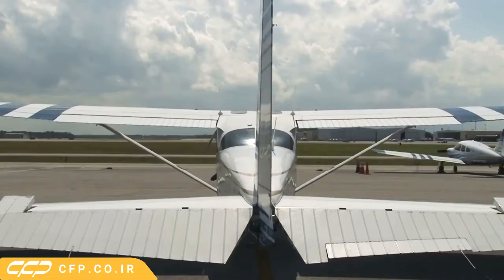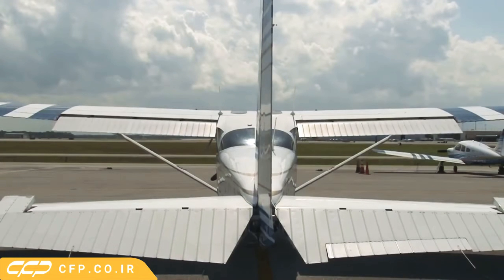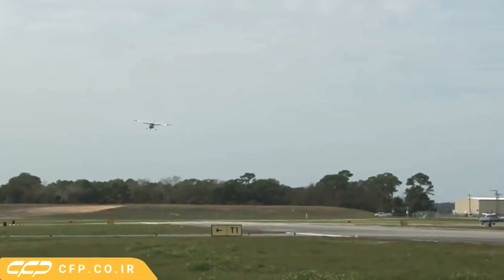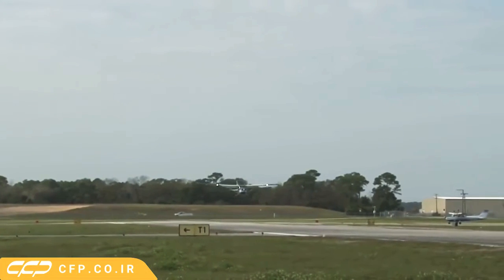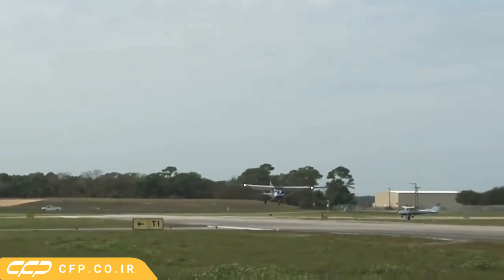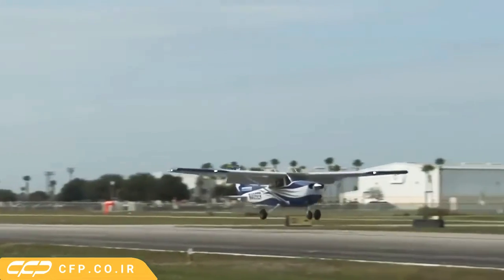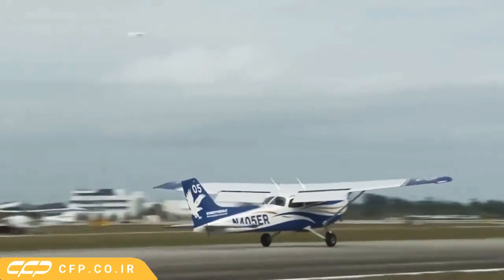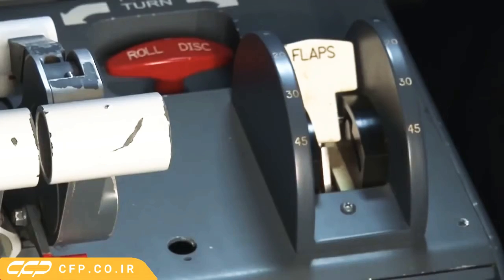These are called high-lift devices, the most common of which are trailing edge flaps, or just flaps for short. High-lift devices, such as flaps, are designed to increase the lift and drag generated by the wings at low airspeeds. Flaps are particularly important for the approach and landing phases of flight. Use of flaps during a landing allows the pilot to fly at a fairly steep descent angle without gaining airspeed, and allows the airplane to touch down at a much slower airspeed.